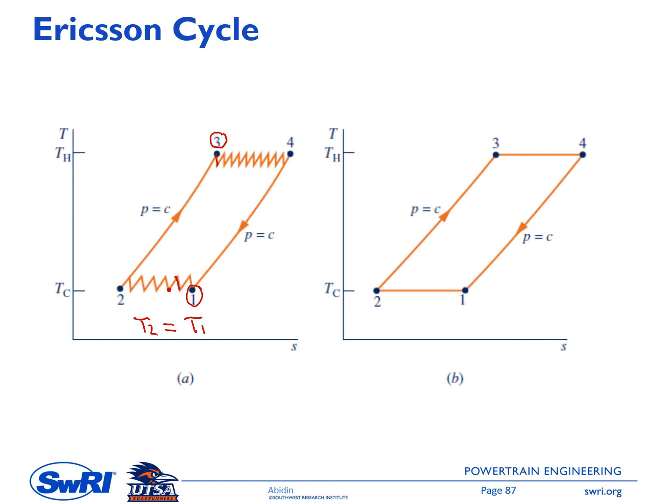Then the reheater increases the temperature back to T3 here, and it enters the second turbine, and then the second reheater brings the temperature back to T3 again, and so on, so that at the exit of the last turbine, this is T4, the temperature is the same as T3. So each reheater brings the temperature back to the temperature at the entrance of the first turbine.